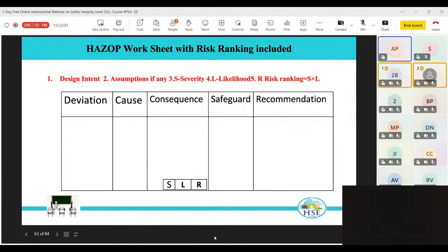please look at making the PSH2 loop safety critical. That means an SIL may be calculated, and an assessment may be done for this particular loop. This kind of thing. Now, I very quickly captured this, this is the way the discussions go, and this is the way the recommendations will come out of this.